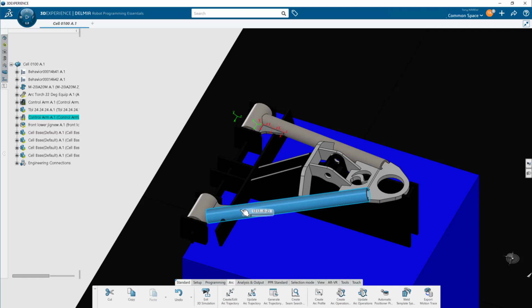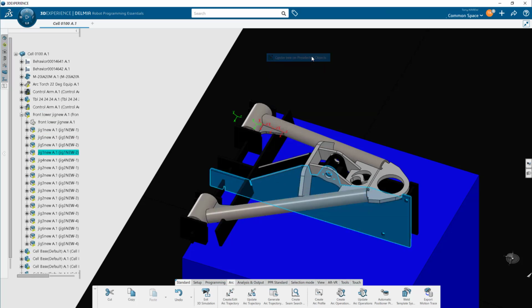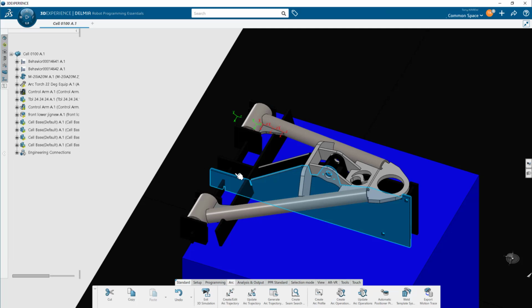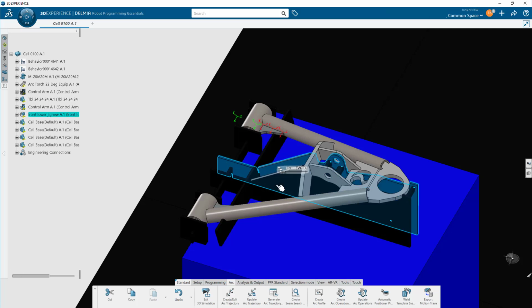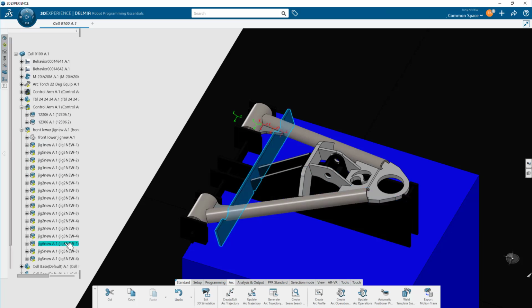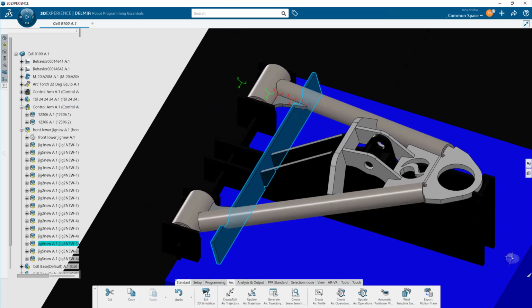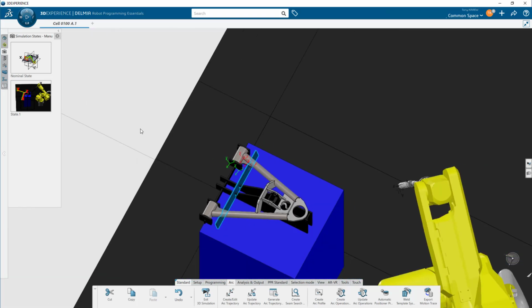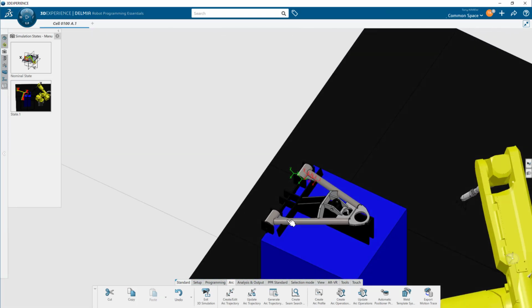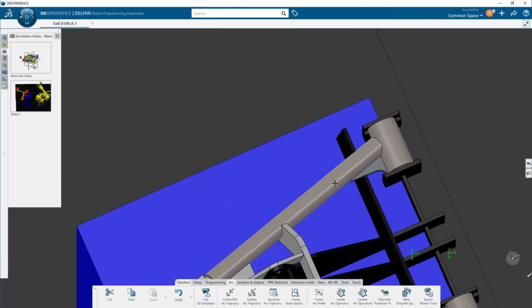Here's a helpful hint for you. If you're ever trying to identify where in the tree a part is located, you can always use a right click and then say center tree. And that way the tree will bring you the object. And this also works conversely. You can go inside the tree and locate a specific part and right click on it and say reframe on, and it will bring it into your view. And it makes it easier this way to identify objects and where they're located in the tree or in the world.